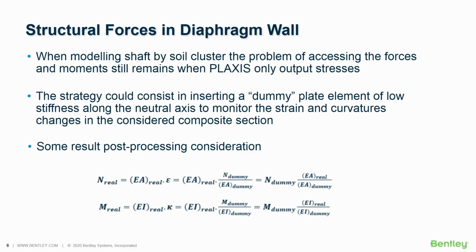Another interesting remark, still related to the modeling of the retaining wall as a solid element, is the absence of structural forces by default when using such type of modeling techniques. Soil elements will only provide, as a result, stresses through the wall, whereas you are most likely interested in structural forces along the neutral axis of the wall.